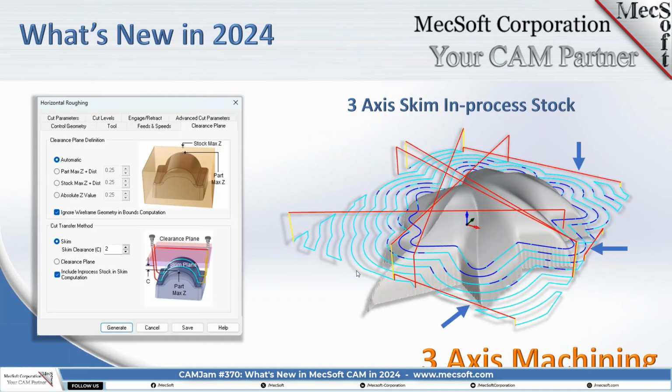The 3-axis option here allows you to skim across the in-process stock. If you look at this picture on the right, you'll see that when the tool has to clear the part, it will retract to the full position on the clearance plane. When it just needs to move from one point to another on the level that it's cutting, it will obey a skim clearance. So this is a combination of clearance plane and skim clearance together and uses them optimally.